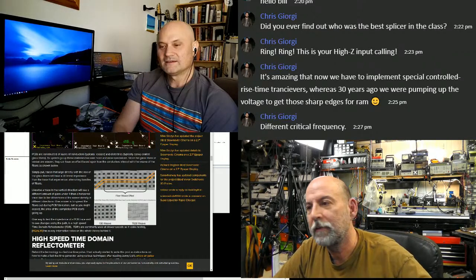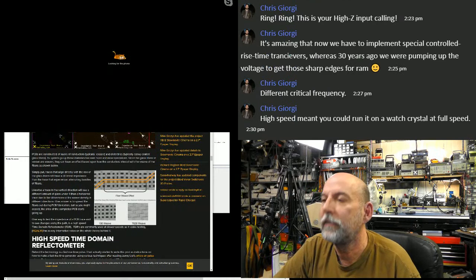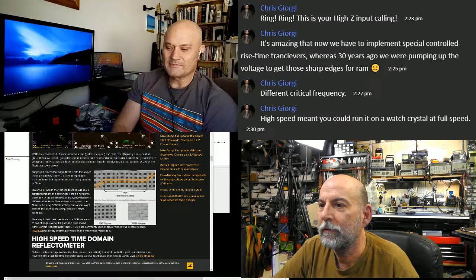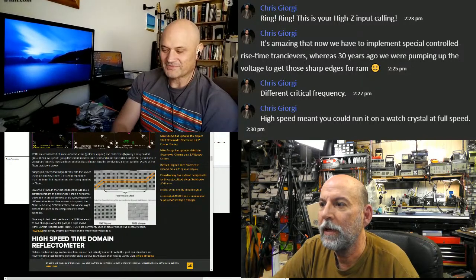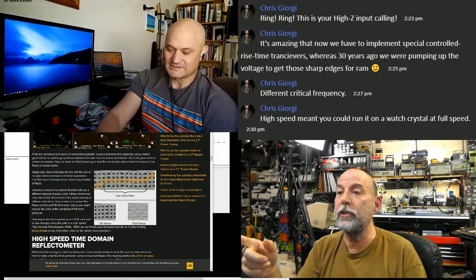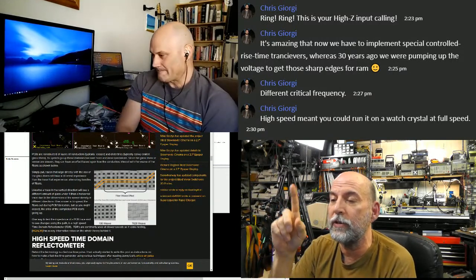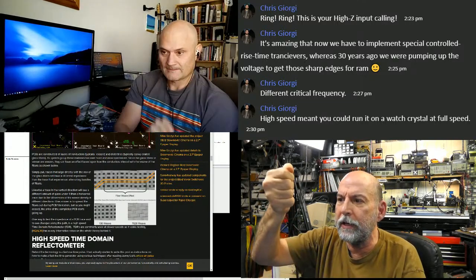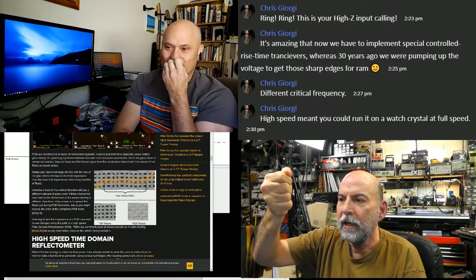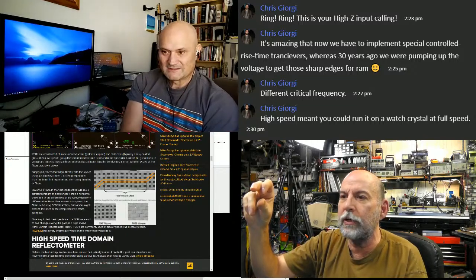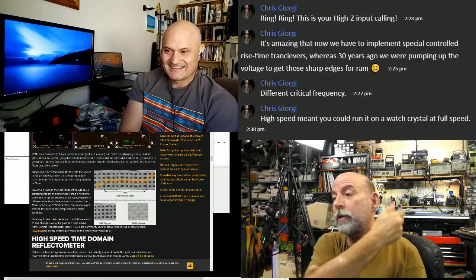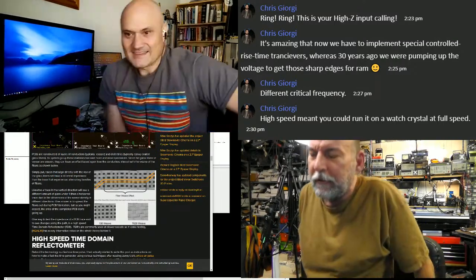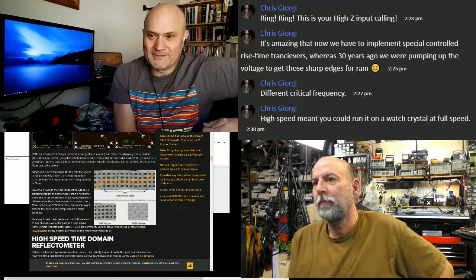There are some actual guitar overdrive and fuzz pedals that use... There you go. They use the 4049 as a high gain amplifier. I really did ultrasonics that way, using a 4001 with a 10 meg feedback, which held the CMOS part right at half VCC. And then I put an ultrasonic transducer in it, which has nothing for current, and it worked. Gain was like 10,000, something like that. It's a poor man's high gain op amp.